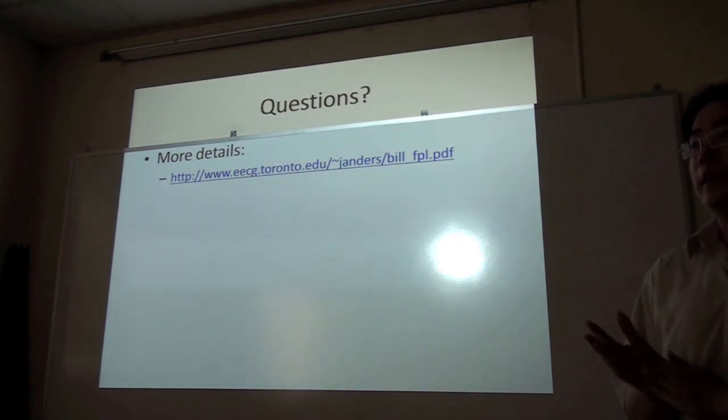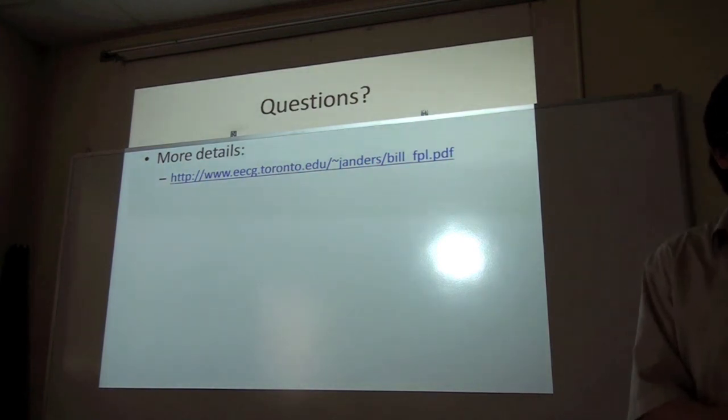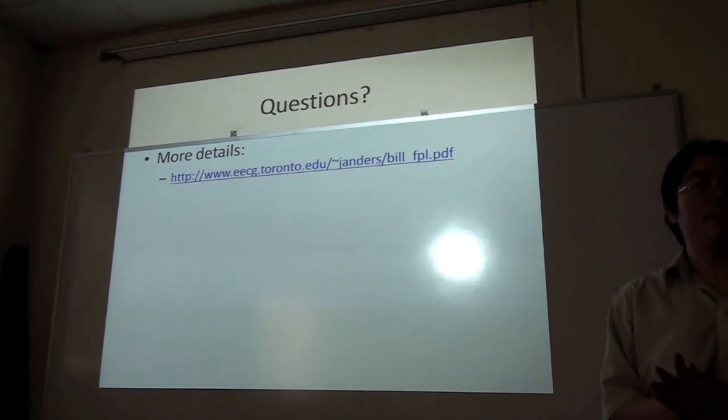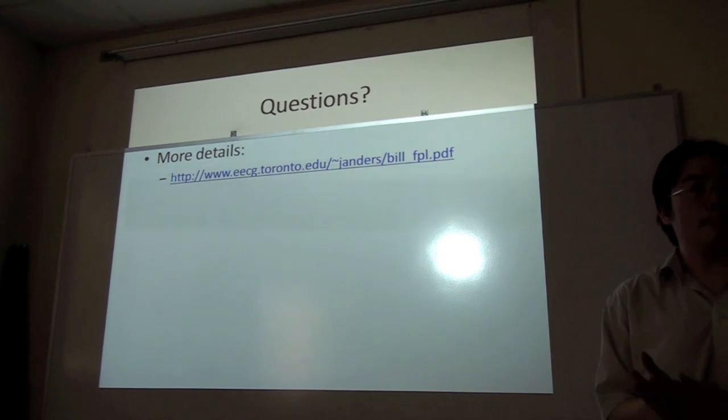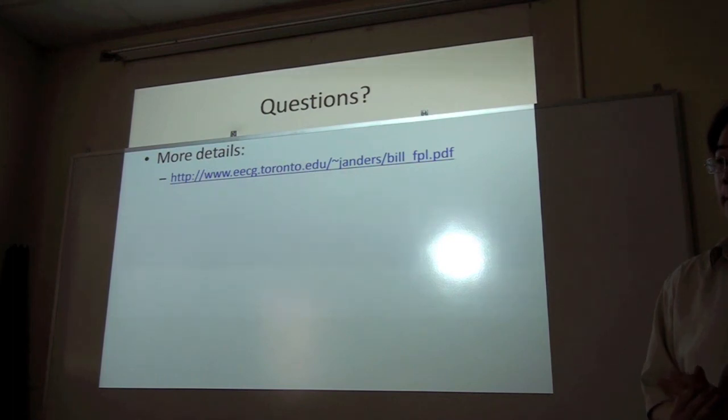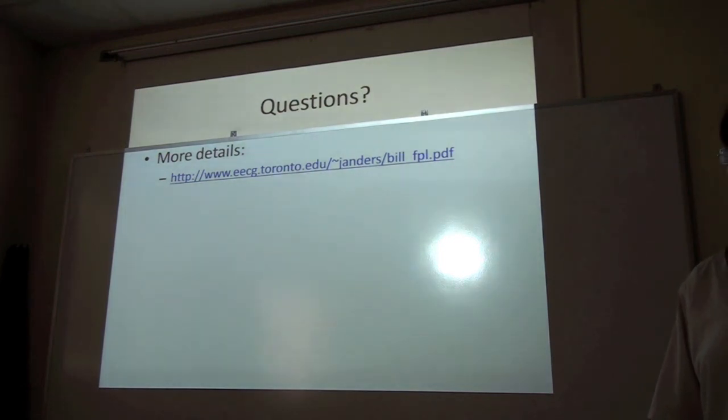Any other questions? So maybe Dave might ask, in terms of process variations, how much variability do you get in a delay path? Well, you get lots. You have VDD, you've got process, and local variation, so it's huge. Probably more than 2 to 1, but it's also correlated. In this case, you're generating 2 clocks that are probably going down similar paths, and they've got roughly similar process corners and similar VDDs, so you can take advantage of correlation. Okay, thank you, Steve.